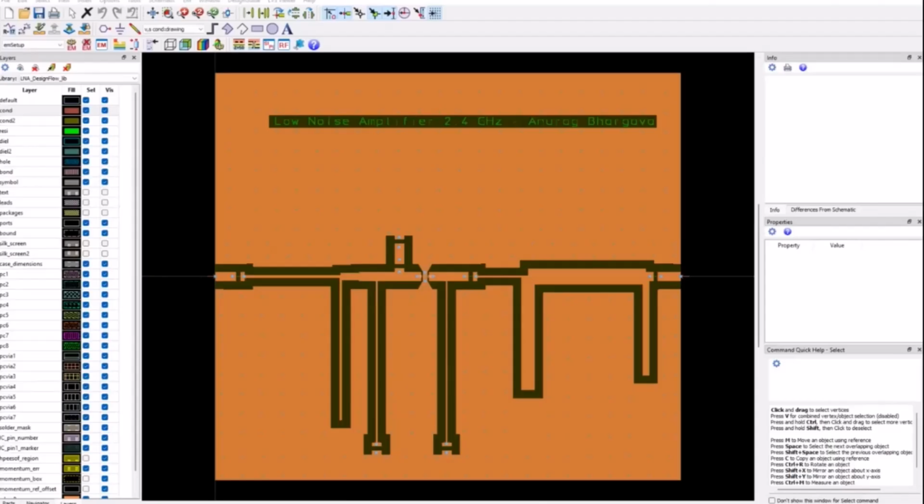In some cases, BPF is used as a first stage of receiver. Yes, absolutely. Sometimes you will have BPF right at the input, and that will impact the overall noise figure performance of the receiver, and you can't do anything about it. You need to just take it into account while doing proper system budget calculations and so on.